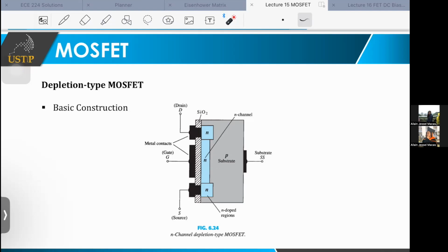Okay? So, the gate here class, same as your JFET, controls your voltage, controls the pinching. And consequently, it will affect your drain current, whether its value decreases or increases. It is the same here in your MOSFET: your gate creates an electric field that either attracts or repels charges. So that phenomenon will modulate the conductivity of your MOSFET. So that's too technical.